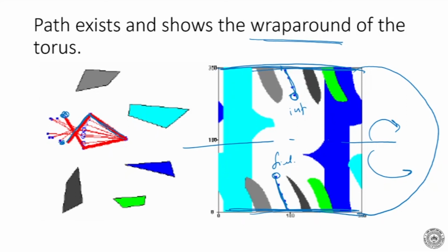So this is something that we looked at in today's class. We talked about ways of drawing the Cartesian space. Today's class we talked about how to draw the Cartesian space for a serial arm robot. And after you make the Cartesian space for the serial arm robot, if you have to find a path, it has to be path connected, which means that in the manifold there should not be breaks due to the obstacle, and the initial point and the final point should be connected in the manifold itself.